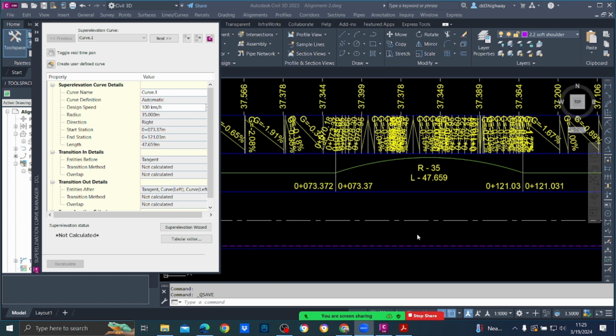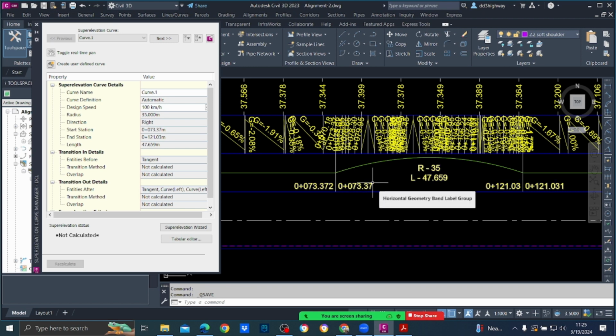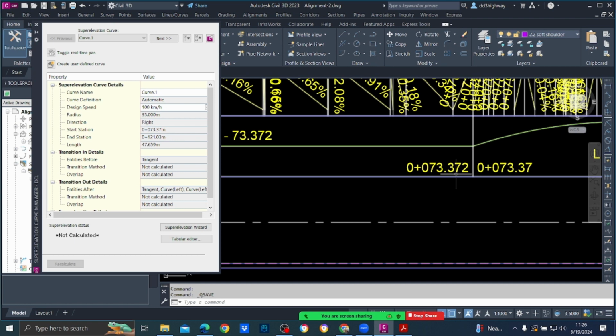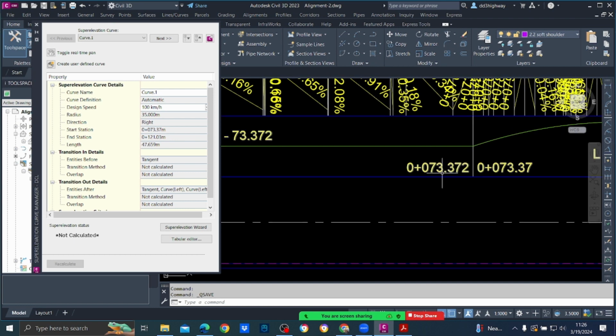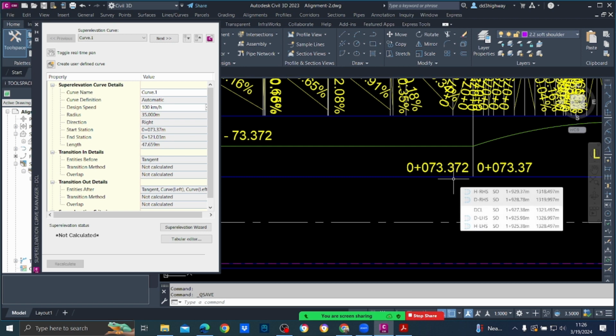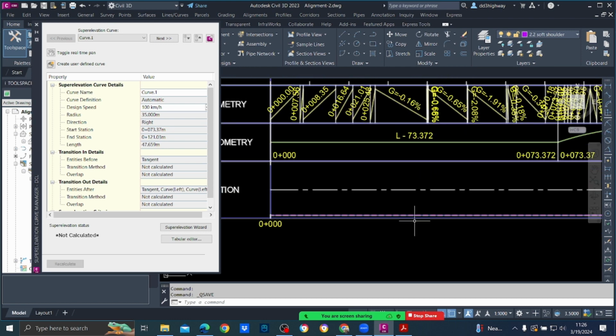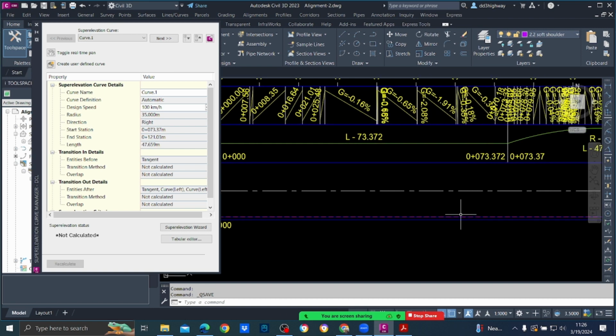So first we'll calculate. Now you know it is 33. One third of 33, how much? 11. And two thirds is 22. Here the curve starts at 73, taking the nearest integer. 73 minus 22, how much? 51. So your normal crown is ending at 51.